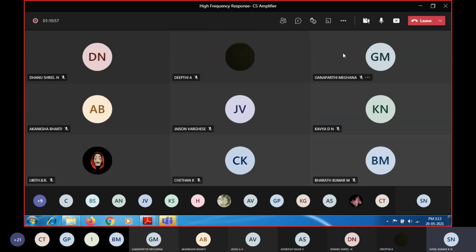So what is Miller effect? Even I will also do it in the next chapter. So before that, since between gate and drain we are going to have a capacitance, it is going to be connected between the input and output. So the capacitance cannot be considered as the input side as well as the output side. So whenever we are going to have a feedback like that between the input and output, we are going to consider that effect as the Miller effect or Miller multiplier.